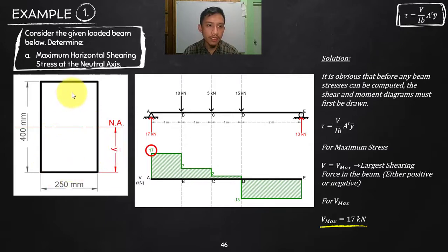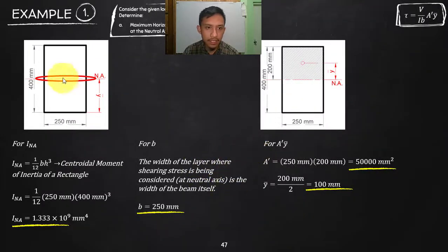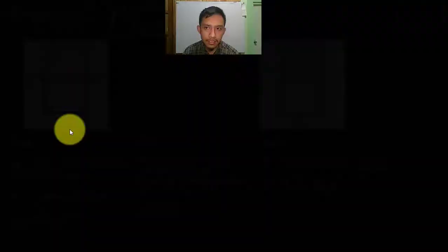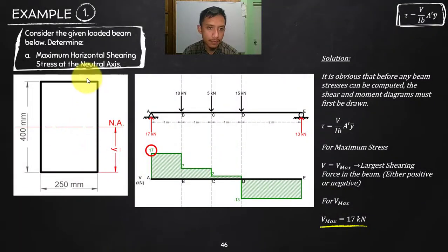Therefore, it means that if I take the moment of area of the top with respect to NA and then the below with respect to NA, they should be equal. I will show you that in this example, or on the next example, because here it is obvious. Since the C here is just half of the height, using either the below or the top will give us the same.